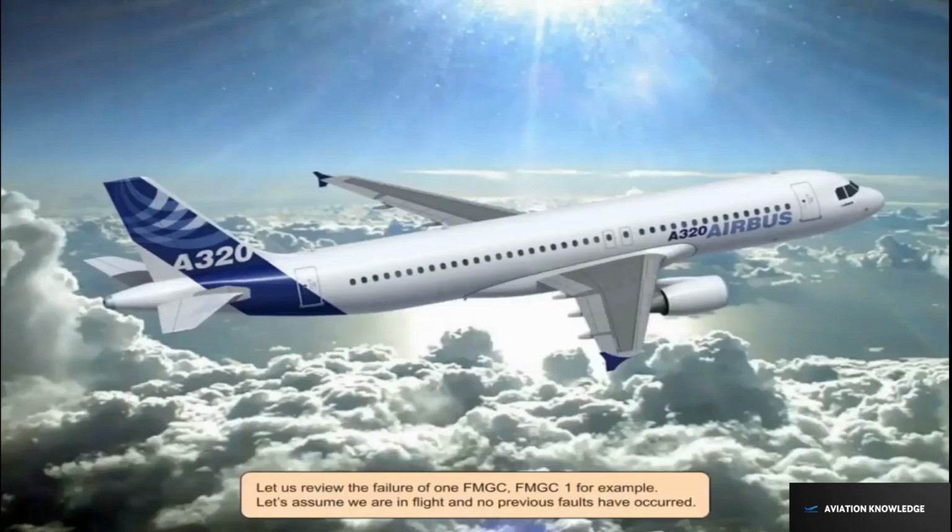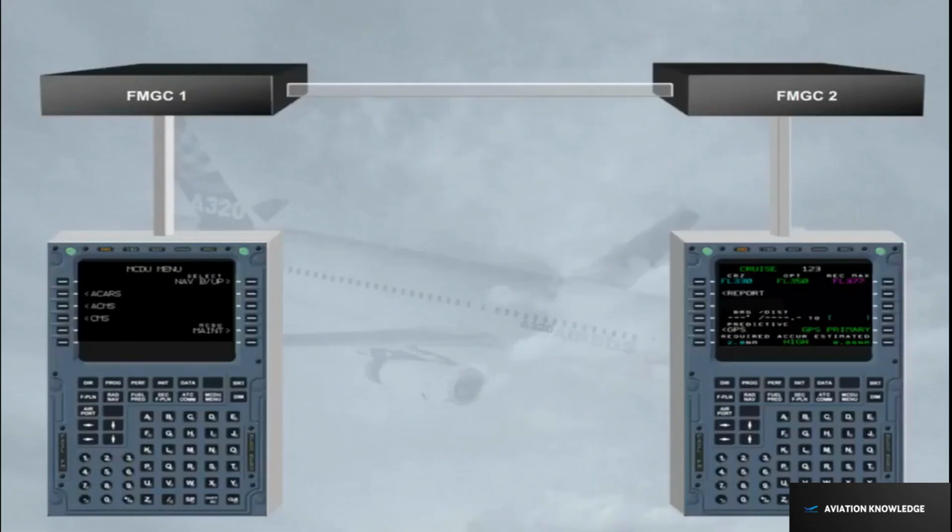Let us review the failure of one FMGC, FMGC 1, for example. Let's assume we are in flight and no previous faults have occurred. If Autopilot 1 and Auto Thrust were engaged, Auto Flight AP off and Auto Thrust off are triggered on ECAM. AP1 and Auto Thrust go off. Note: you can re-engage the AP on the healthy side, in our case, AP2. If Auto Thrust has disengaged, it can be re-engaged at the same time.